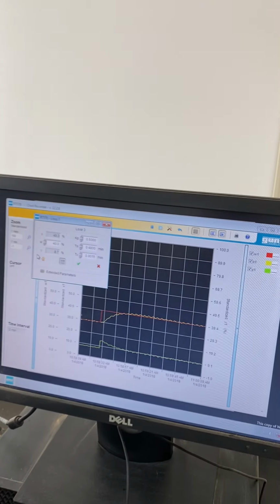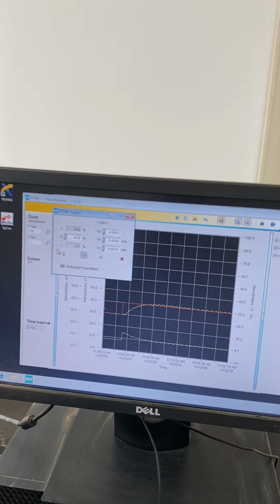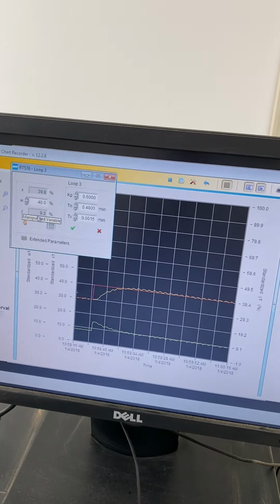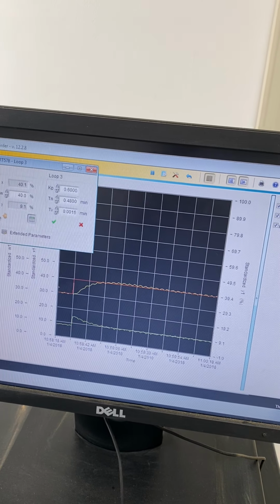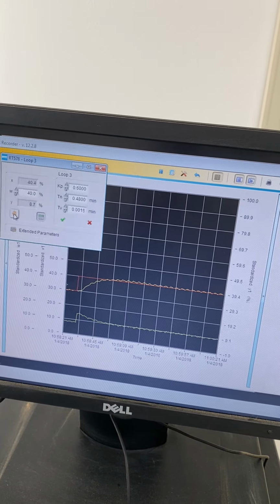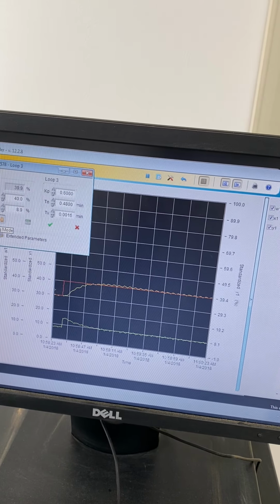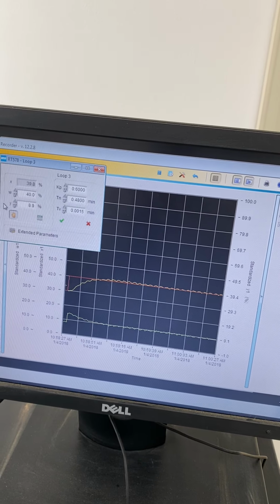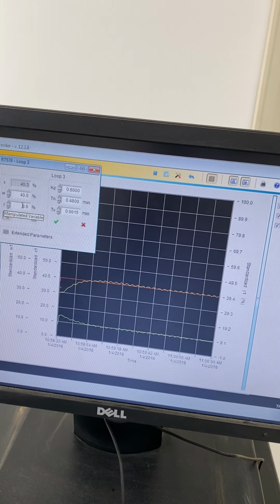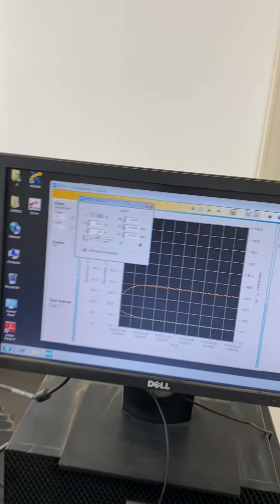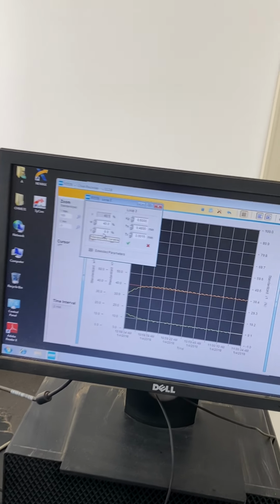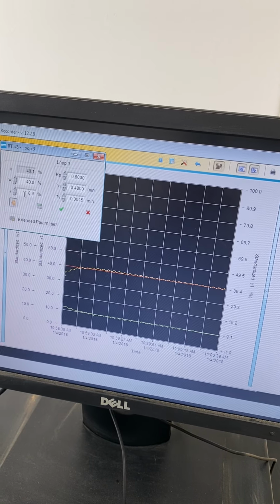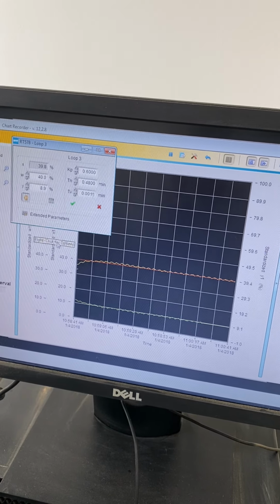If it takes longer than usual, guys, and if it feels somewhat inconvenient for you as an operator of the system, then you can switch to the manual mode. That's where the output signal is manually changed. Okay, notice the output signal is constant. That's why I made this change. I switched to the manual mode to show you that even at a constant output signal, the pump speed is now constant.